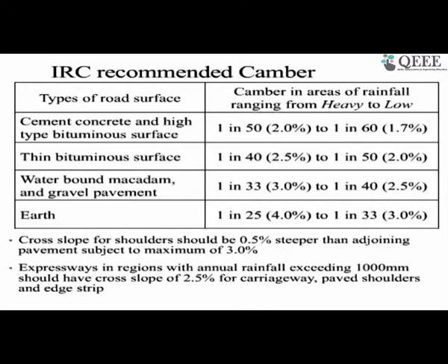Okay, so now before I move to the next slide, I got another question. The question is, is camber also required for porous concrete pavement? Generally, porous concrete pavement is not used on the travel path. So far what I have seen or known is that porous concrete pavement is generally used for the sidewalk, and that is a common practice in the US. I have noticed that they are using it in the sidewalk. In the porous pavement it can be flat, and on the travel path, if it is not porous, definitely you have to make sure that it has some camber.